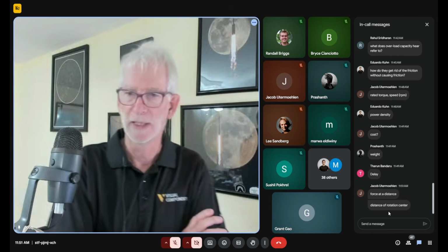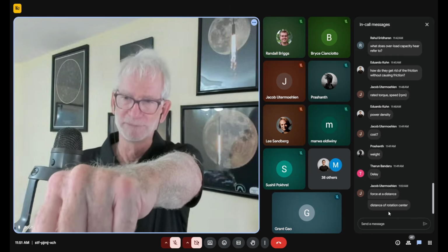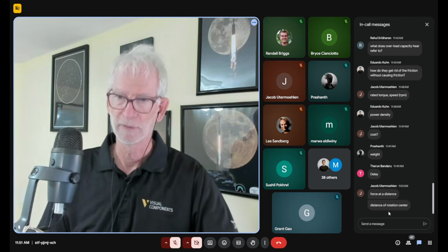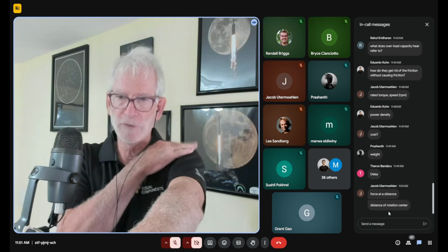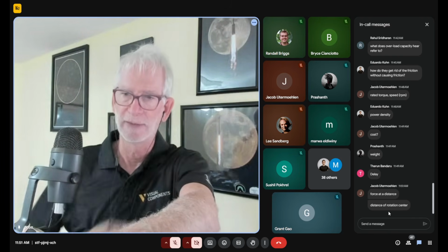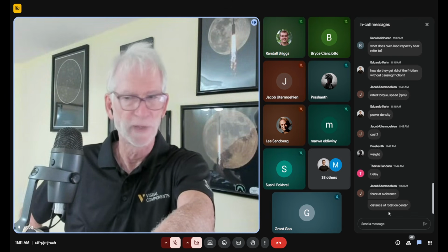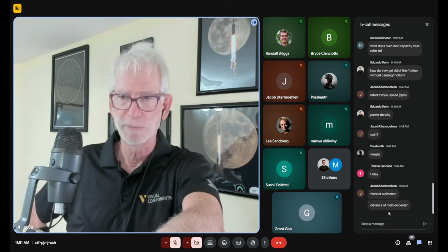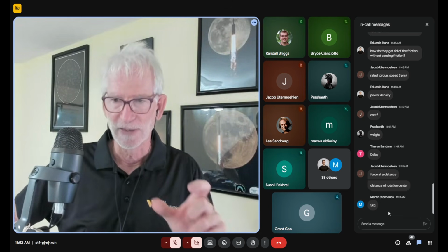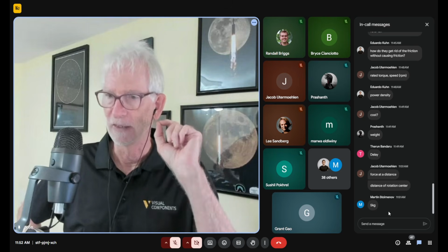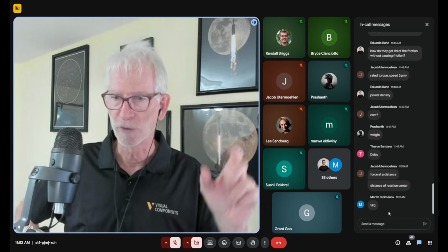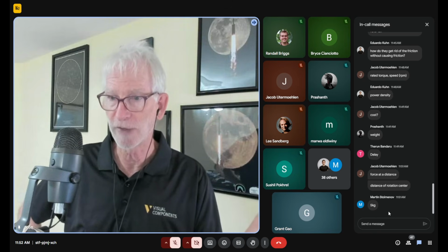An example of something about a meter long is my arm. If my arm is straight out and I want to lift something, and I'm applying 50 Newton meters back here in my shoulder, how much mass can I lift? Most people are not familiar with newtons, right? So what's the relationship between newtons and mass? Yeah, exactly. The relationship between them is g, which we can approximate as 10 meters per second squared. So if you take 50 and divide it by 10, you've got 5 kilograms.